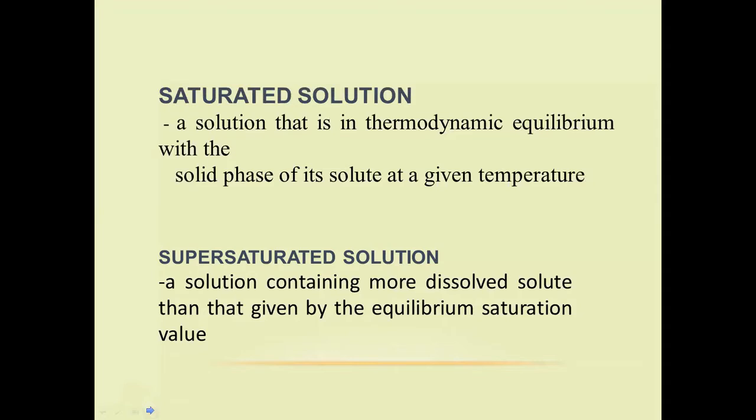Now, when we speak of crystallization to happen, your solution has to be in what we call saturated condition or supersaturated condition. Otherwise, we won't have the growth of crystals, or we won't even induce the growth of crystals. When we speak of a saturated solution, we learned this in thermodynamics, it's a solution that is in thermodynamic equilibrium with the solid phase of its solute at a given temperature.